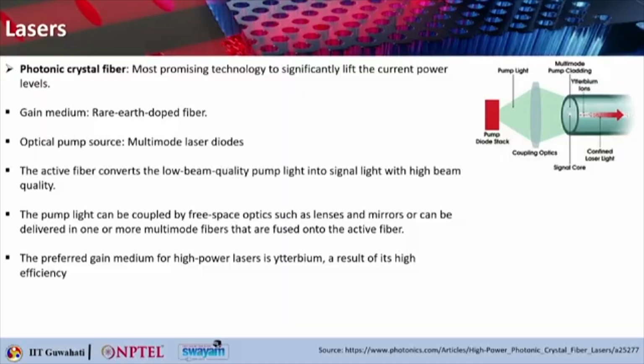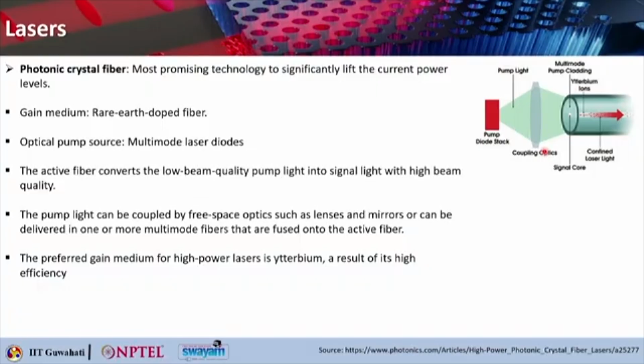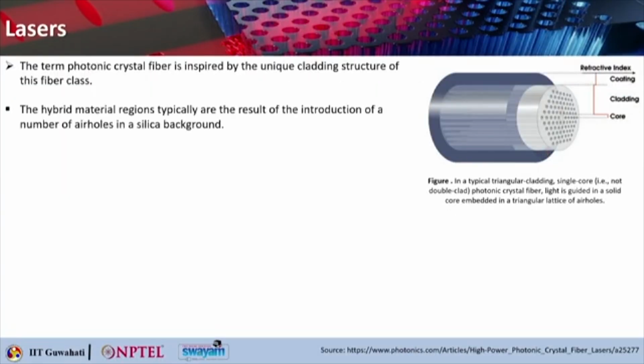Photonic crystal fibers are perhaps the most promising technology to significantly lift the current power levels, because of their increased flexibility in the single mode core size. As you can see here, there is the increased numerical aperture of the pump cores in double clad fiber configuration, and also the high thermal stability of the low loss all glass structure. These are a couple of the features which enable this photonic crystal fiber to deliver good quality lasers. The term photonic crystal fiber is also inspired by the unique cladding structure of this fiber.